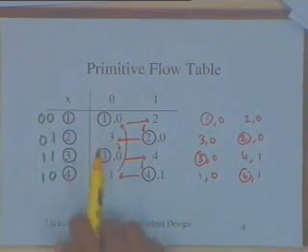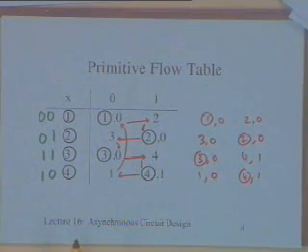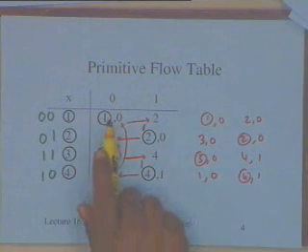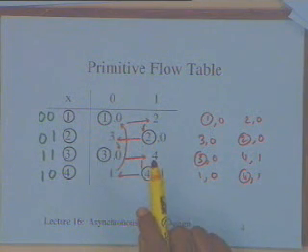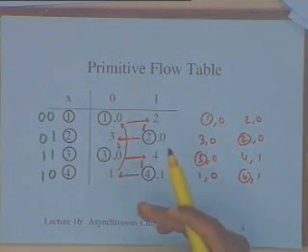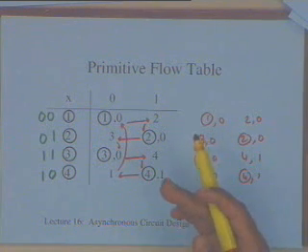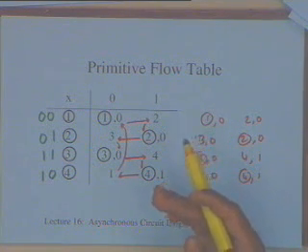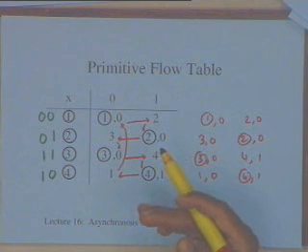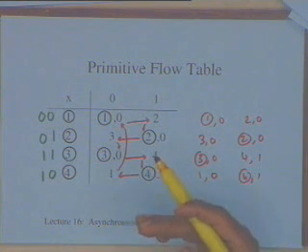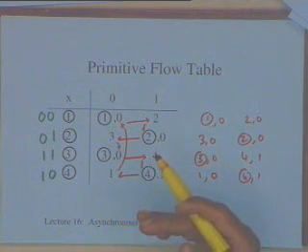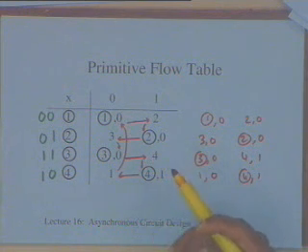So in this particular case, a critical race results because there are columns in which there is more than one stable state, in this column also and this column also. When there is more than one stable state, and still you want to make the races non-critical, that is, you should actually go to the final state, you have to bother about your state assignments. You have to do your state assignments in a manner so that you will reach it.